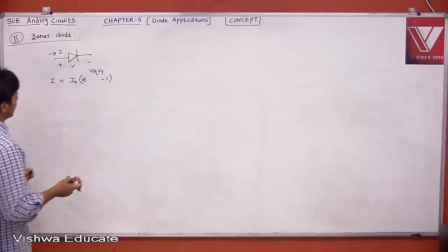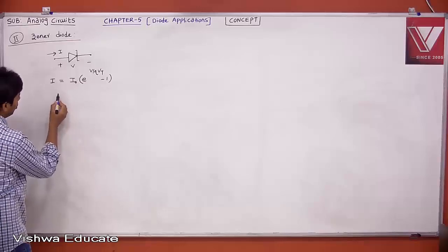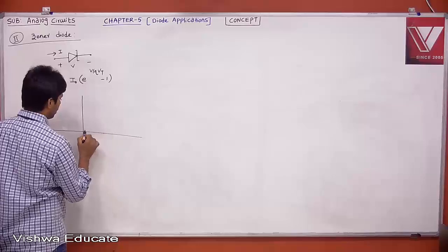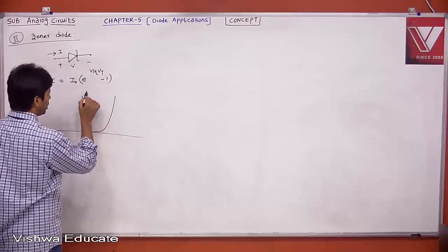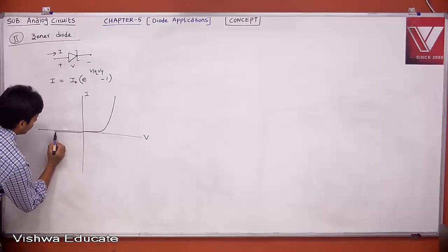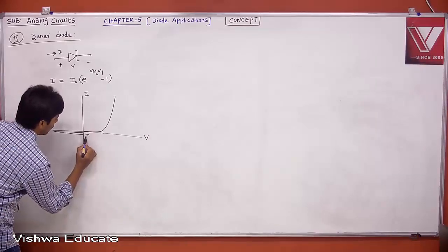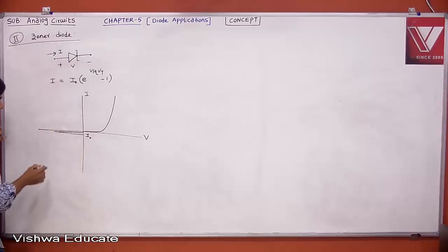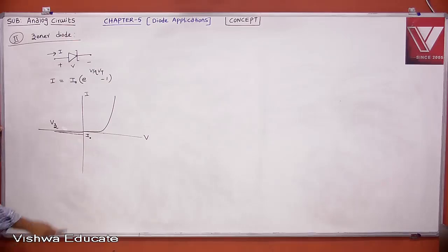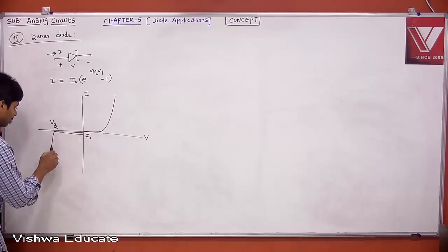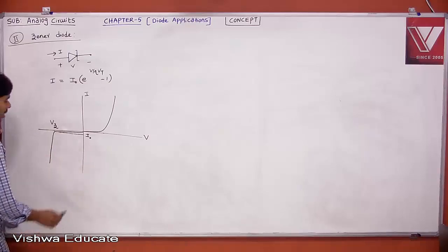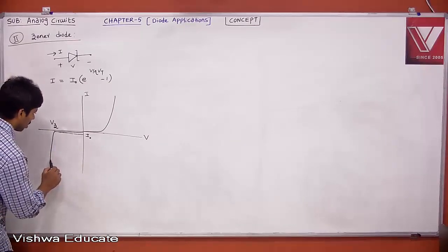If you take the exact model of this Zener diode also, it will be like this up to V gamma. Current is not significant. After that, it is increasing exponentially. This is I and this is V, and this is almost 0. This is what people call your I naught, or Zener leakage current. This is your breakdown voltage, people call it VZ. We try to operate there, because it is a controllable phenomenon. But we should not cross something, that is what people say.